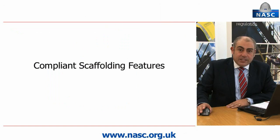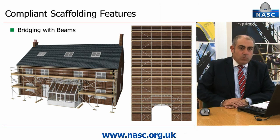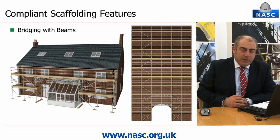We're now going to look at the scaffolding features within TG20. We see the welcome introduction of bridging with beams, with standard configurations for 2-bay bridges and 3-bay bridges using steel ladder beams or steel unit beams, and a design criteria for the use of other types of prefabricated beams such as aluminium beams.